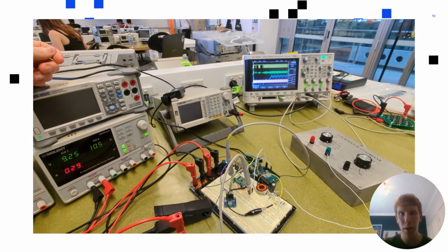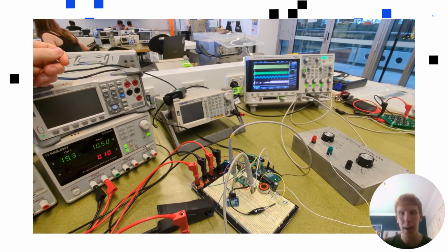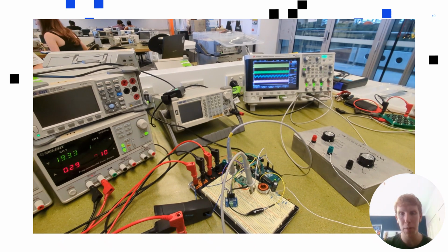Here, if I play the video, it is in the current steady state, and observing the oscilloscope, we see some jumping in waveforms, which is indicating that the GA algorithm is activated, and quickly going back to the INC algorithm and its steady state operation.